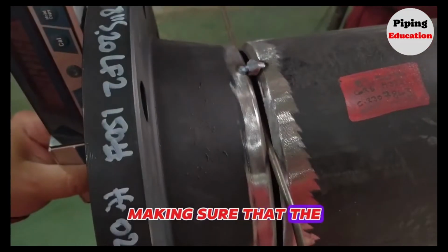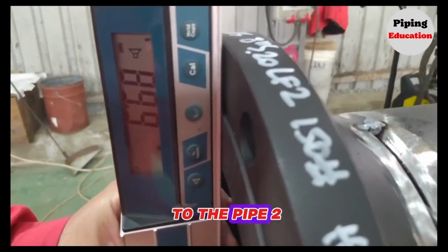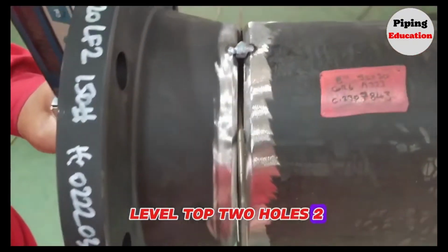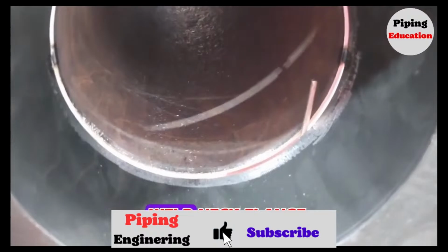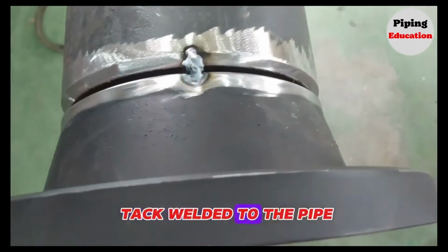After making sure that the top 2 holes are at the same level, we tack weld the weld neck flange to the pipe. And again we check the top 2 holes with the level. After making sure that the level does not change after the tack weld, we tack weld the weld neck flange to the pipe in 3 equal places. Now the weld neck flange is tack welded to the pipe.